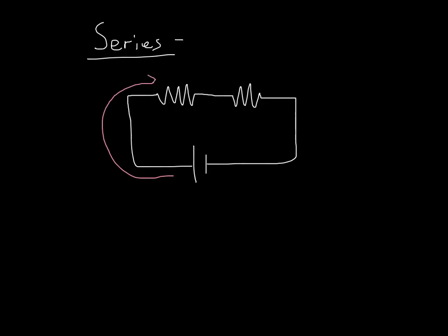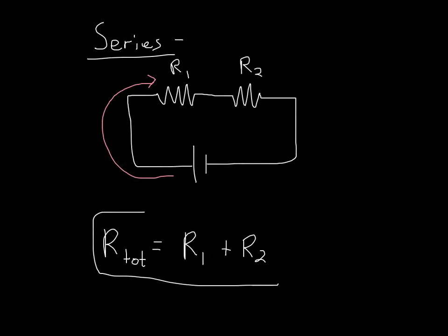It can't go through a choice of the first or second resistance. So the resistors are in series with one another. One follows another. The total resistance in this case is going to be equal to the first resistor plus the second resistor. Resistors in series add normally. You don't have to worry about fractions with those.